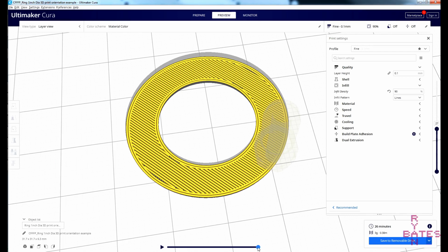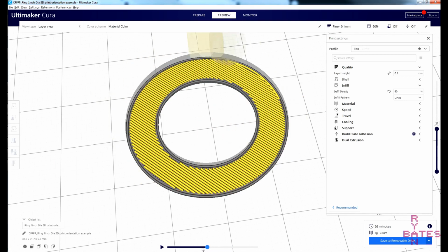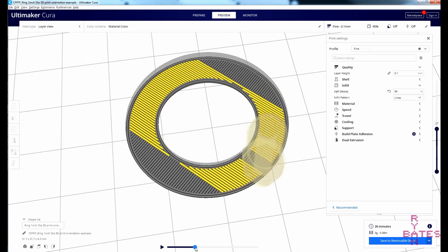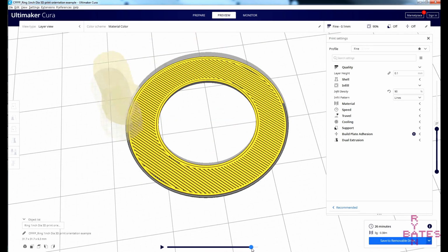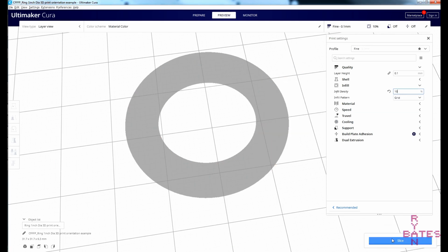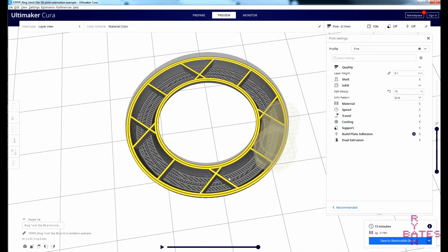The higher the infill, the more material is consumed to build your part. Remember, using more filament inherently drives up the cost of your part. A 100% infill for a part that is still at the proof of concept phase is not a good use of resources. Another downside with higher infill percentages is more material means a longer print.